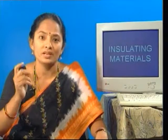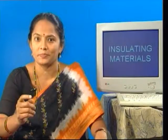The next property is dielectric strength. Every electrical apparatus is designed so as to work within a defined range of voltage. If the operating voltage is increased gradually, then at some value of voltage a breakdown will occur, puncturing the insulation permanently.